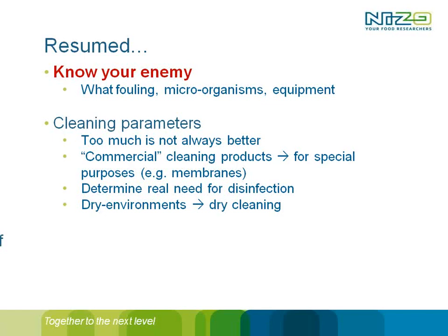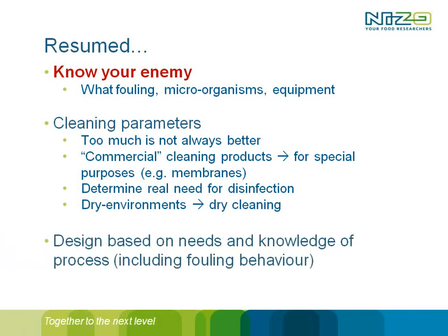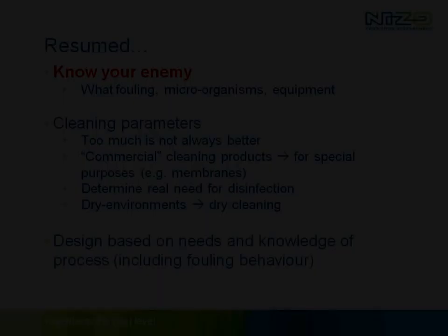And in dry environments, try to do a dry cleaning and try to avoid wet cleaning as much as possible. Your design should be based on needs and knowledge of the process. So think about your fouling behavior while designing a process, and don't do it afterwards when you build your plant and you're trying to solve the problems, since changing an existing configuration is usually much more effort than doing it in advance.